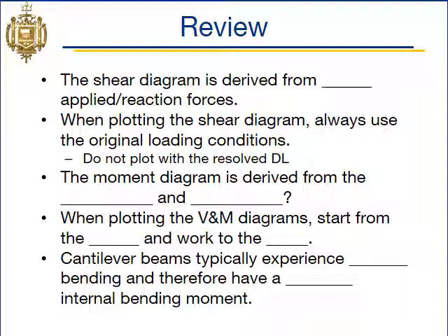All right, here's our review. The shear diagram is derived from the vertical applied and reaction forces. If you have an angled load coming in, you will get no shear from the X component of that angled load, only from the Y component. If you have a purely X component force, that would just be a normal force and has nothing to do with the shear.